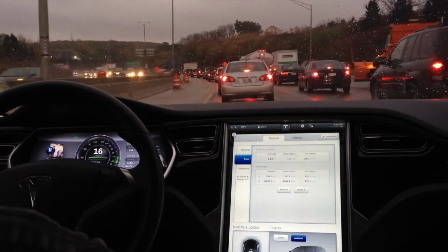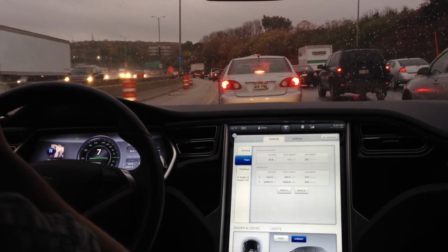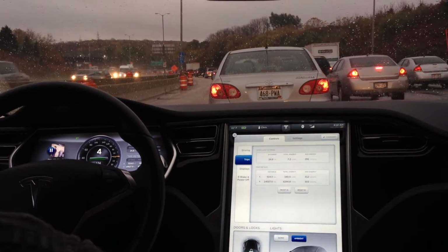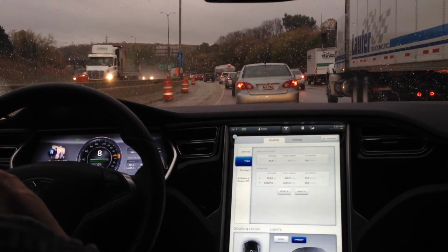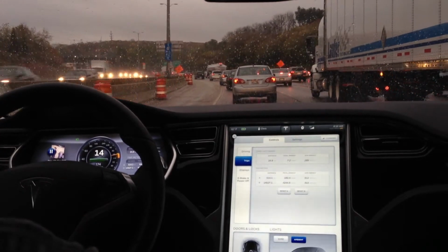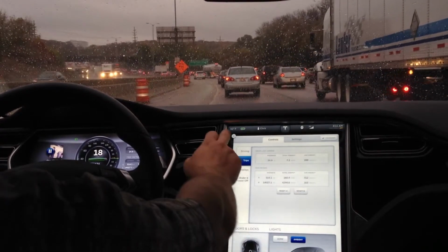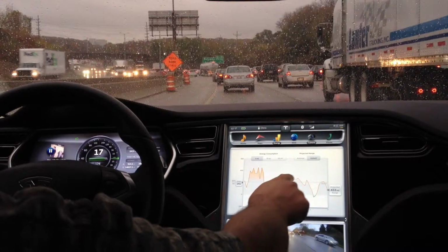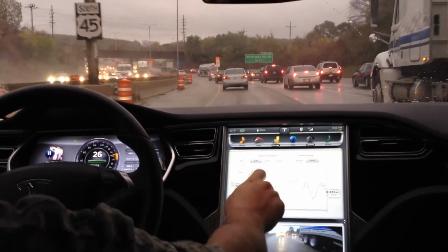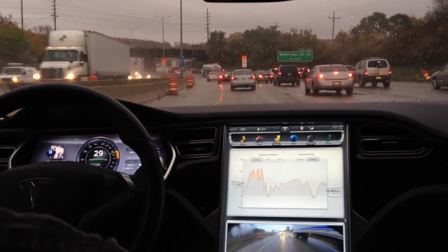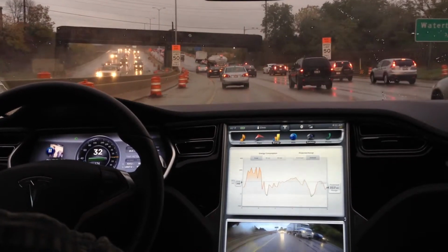So, say I'm drawing 100 kilowatts, which the vehicle doesn't ever need to sustain. Maximum speed of the car is about 125, and at 125, I'm drawing less than 60 kilowatts to maintain speed. But your acceleration, that's where you get the peaks on your energy meter. Peaks are consumption. You're going to draw more during acceleration to get you up to your speed than you need to maintain your speed.